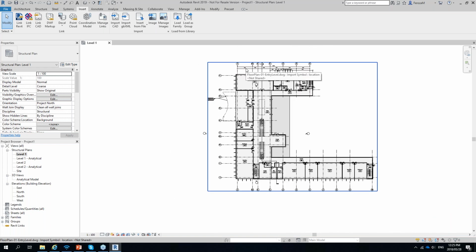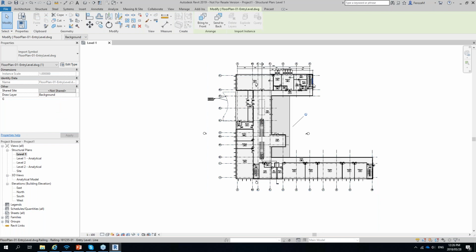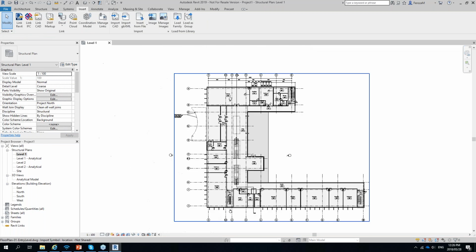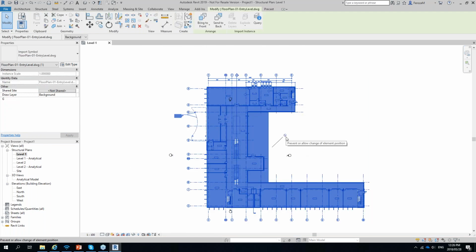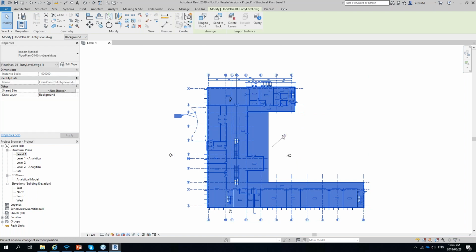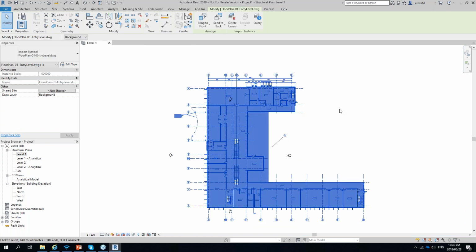Now, when I look at this link here, remember I said that you've got different ways to manipulate the data. If I click on the link, here's the query option, and if I click on it, firstly, you'll see that because I went origin to origin, this drawing is automatically pinned, which means that I can't move it. So in order for me to move it, I'll have to unpin first and then move it around. Right? So remember, if you're linking origin to origin, it's automatically pinned.